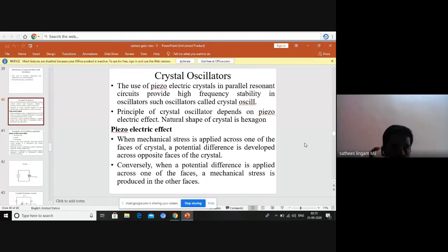That frequency of oscillations itself we are assigning as the timing signal. So for that purpose only, we mostly prefer crystal oscillators. There we cannot use one more board for getting oscillations, like an RC phase shift or Wien bridge oscillator. Likewise, we cannot add one more board. Only one crystal itself is creating the oscillations.